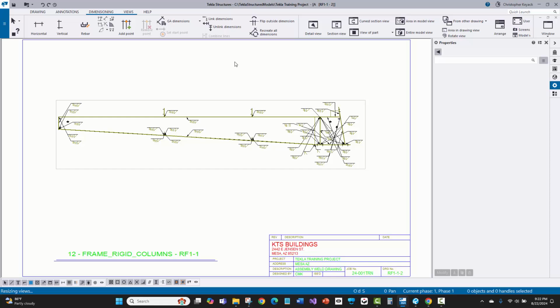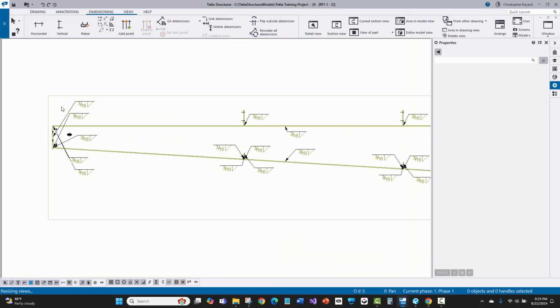and they want a QC drawing to see all the welds that are coming from MBS through SlideRule into Tekla, and they want to validate that and verify that against their shop standards and see exactly what the AGT machine is going to be doing. Now this is one drawing, and I will say this is why I also pull the welds over here on this drawing versus show it on the main assembly drawing.